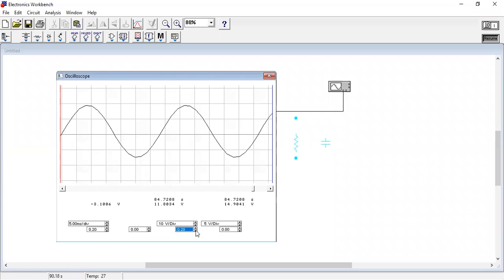The peak is at the third or fourth part of the division. One box is 10 volts, so we can divide it into parts of 1 volt each. There are about three or four parts, so totally we consider four parts, so 4 volts. One box has 10 volts, three boxes 30 volts, and the parts 4 volts, so 34 volts. So the input voltage is 34 volts.